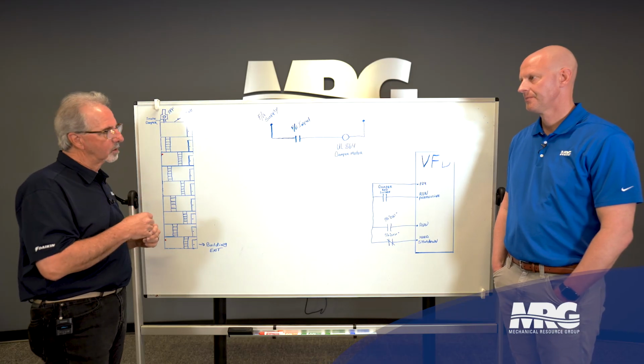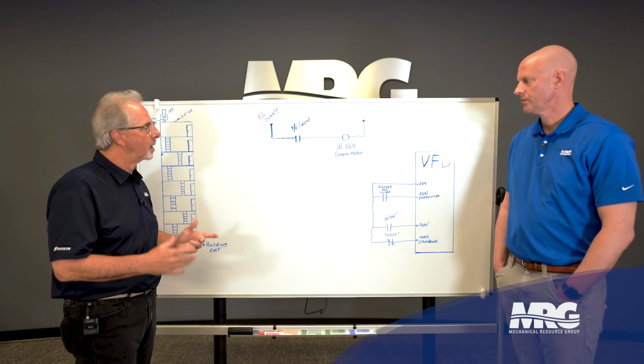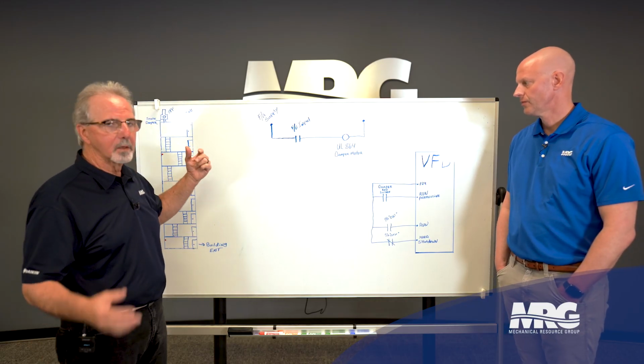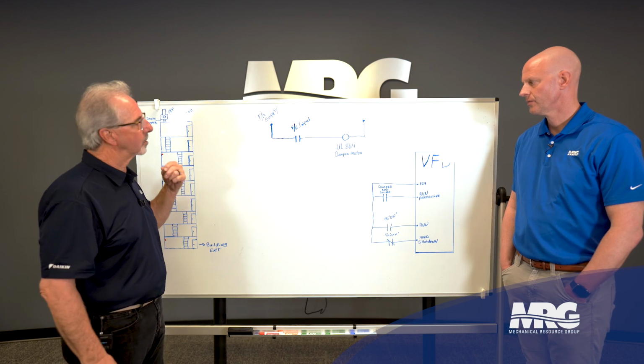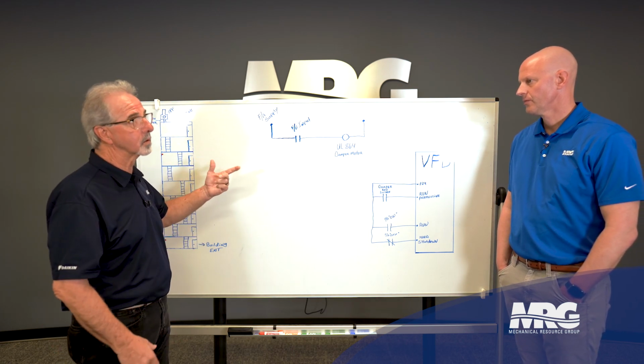What I wanted to show you was a little bit the way that this is wired in, because there is no drive, by the way, you guys, in the world that has a UL864 label on it. It's just not something that they find beneficial. So the way that it works is everything is done by the fire alarm contractor, and he will install relays near the device itself,